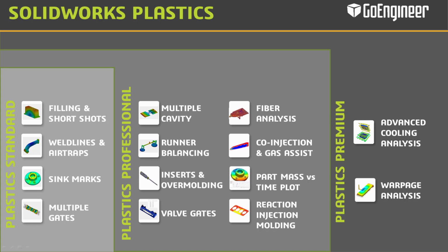SOLIDWORKS Plastics Standard was created for your part designers. It'll answer the questions of, will my part fill, where are my weld lines and air traps. We can look at sink marks and work with multiple gates.